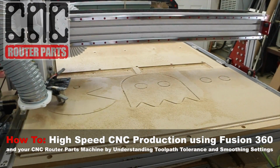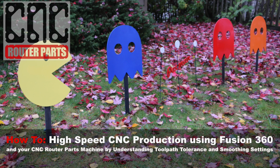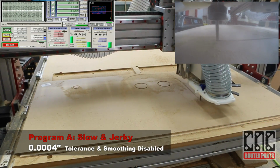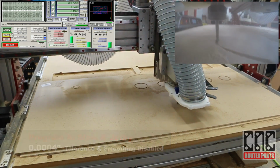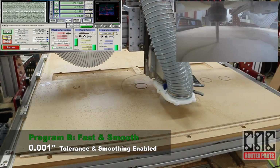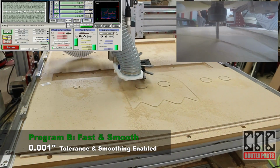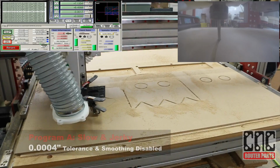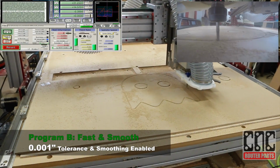Let's start by comparing two programs. Both identical, including a 450 IPM feed rate, except the first one, Program A, I'm using a default tolerance and I've left smoothing off, as it is by default. And in the second program, Program B, I've set the toolpath tolerance to a more practical value, 1/1000th of an inch, and enabled smoothing. And let's watch that one more time. Program A, see it's very slow, and Program B, see we're about twice as fast now and much smoother.